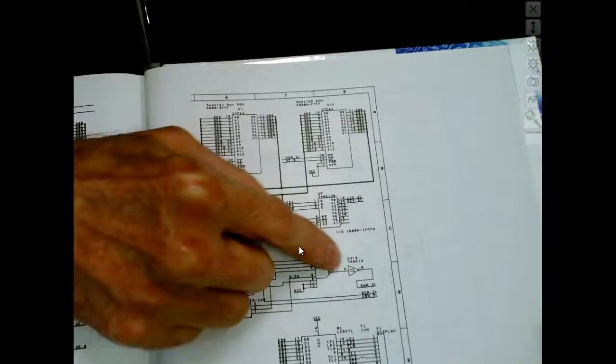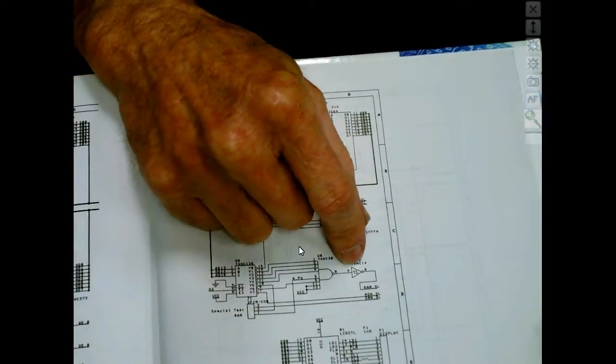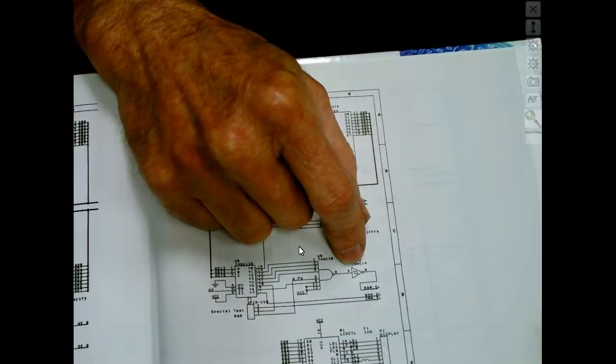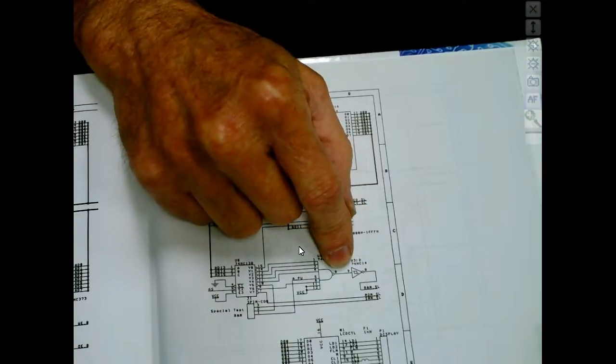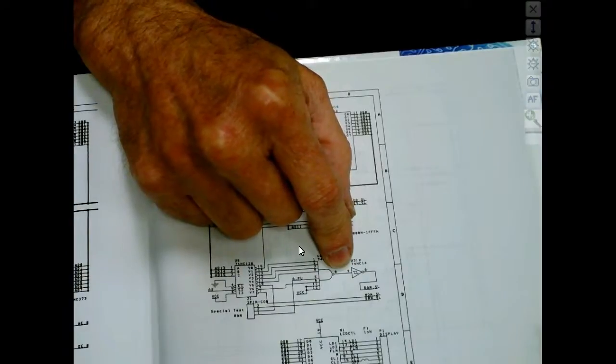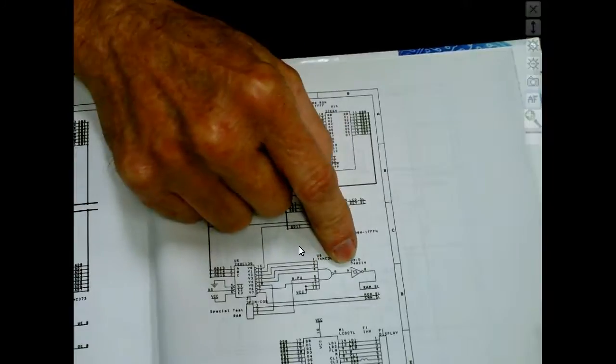These guys right here have a special input on them. These are called Schmitt triggers, and they trigger at a spot. So they'll recognize it as a low until it gets up to a certain voltage. And as soon as it crosses that voltage, it switches. They recognize it as a low as soon as it drops below a certain voltage. And if it sees it as high, the input can meander around all day long, and it'll see it as a high until it goes down to the lower threshold. So these are called Schmitt triggers.